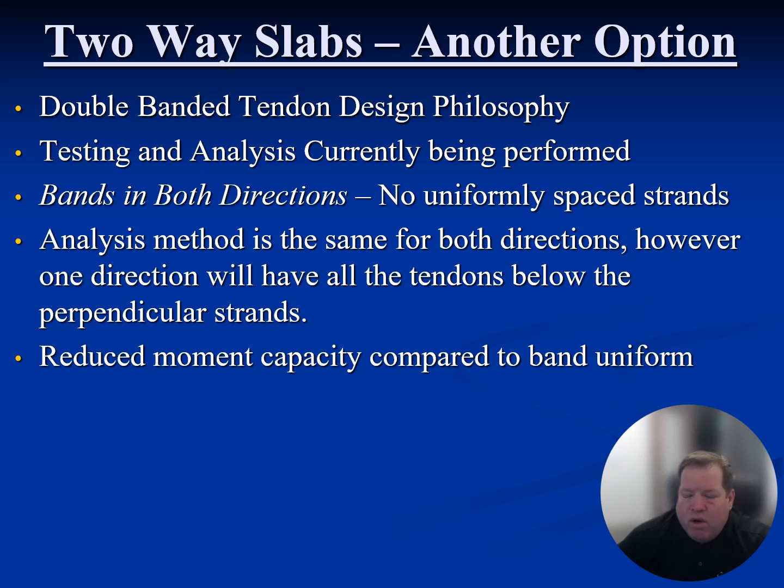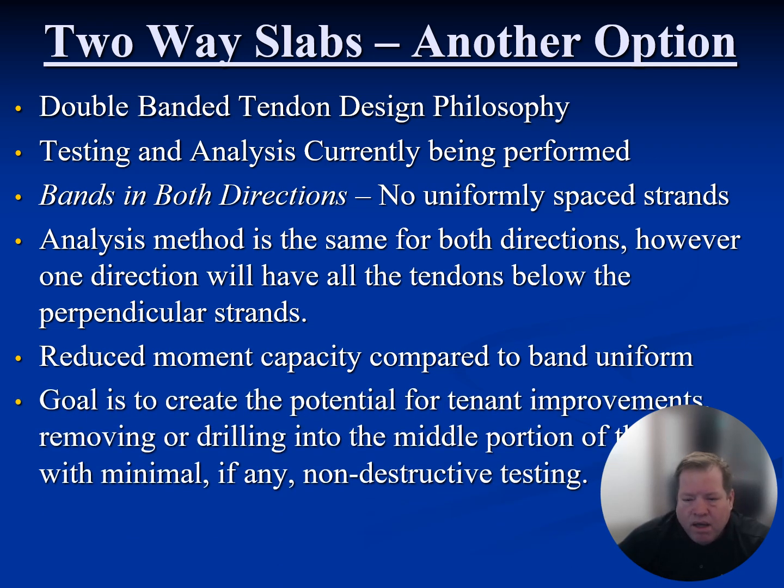So if you really want to be clever and design each direction for a loss of a ½ inch of depth, you can flip the bands in any direction, or however you want to do it. But again, there's a slight reduction in moment capacity, but again, nothing horrific. The reason some engineers want to do that is basically they want to create the potential for tenant improvements.